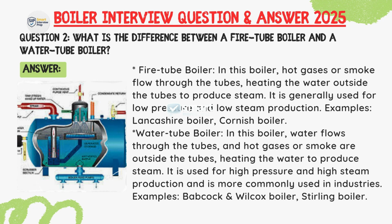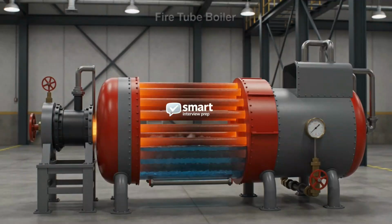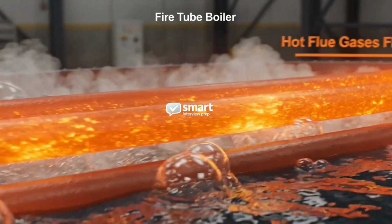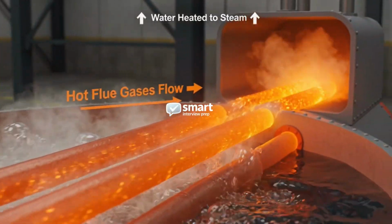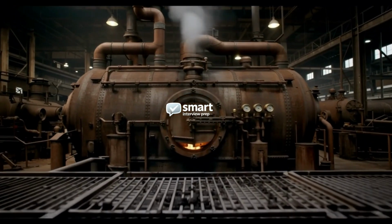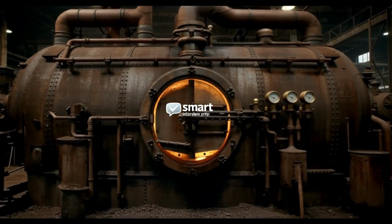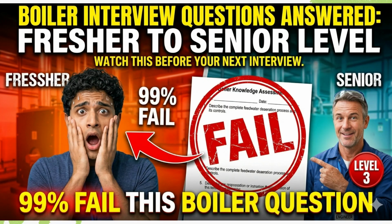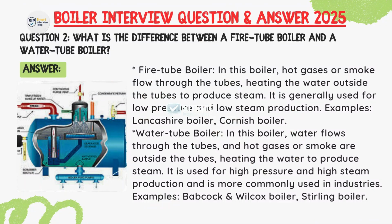Question: What is the difference between a fire tube boiler and a water tube boiler? Answer: Fire tube boiler: in this boiler, hot gases or smoke flow through the tube, heating the water outside the tube to produce steam. It is generally used for low pressure and low steam production. Example: Lancashire boiler, Cornish boiler.